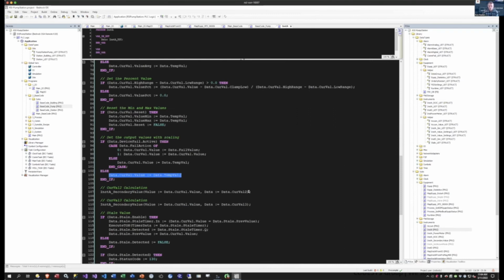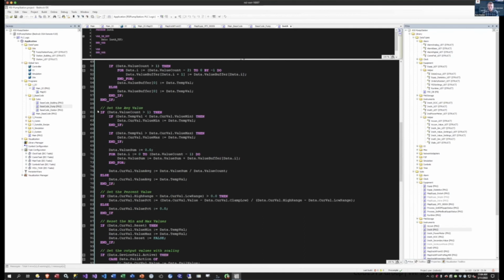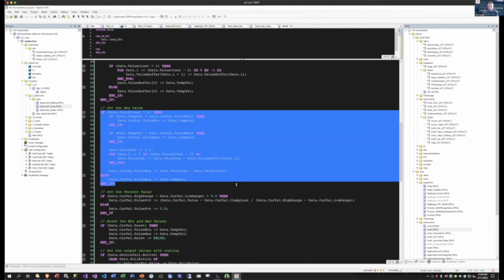I'm looking for whether it's in calibration hold or not. I'm also calculating an average value, which I use a lot, by the way. So this particular task here is looking at the value once a second, and it's filling a buffer of 60. And then I average that buffer. So I get a 1 minute rolling average for this particular value, which when you have really loud, nasty data, that average value can come in really handy at times.